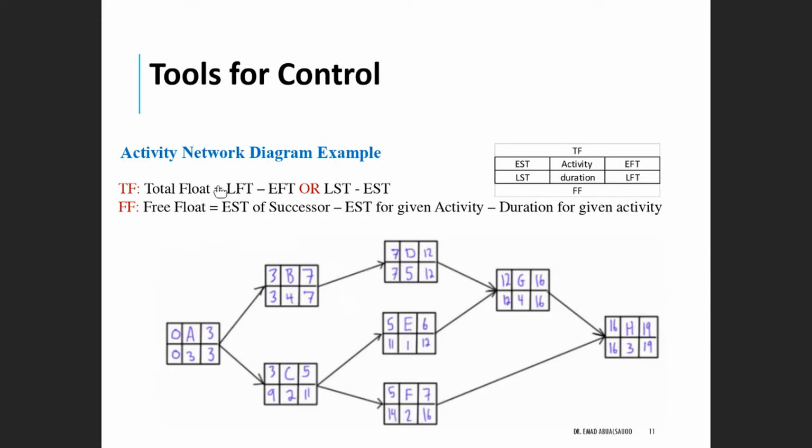The total float is the late finish time minus the early finish time, or you can do the late start time minus the early start time.